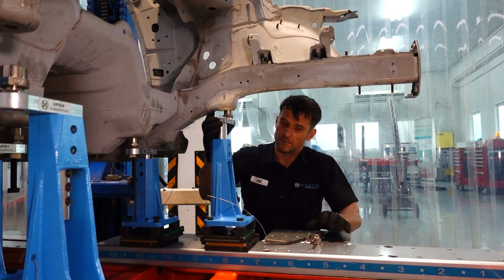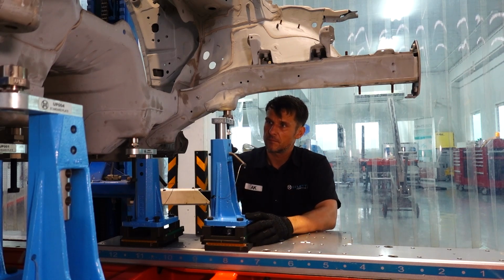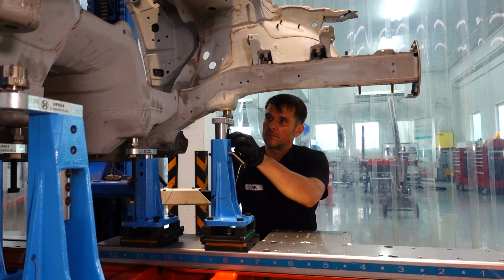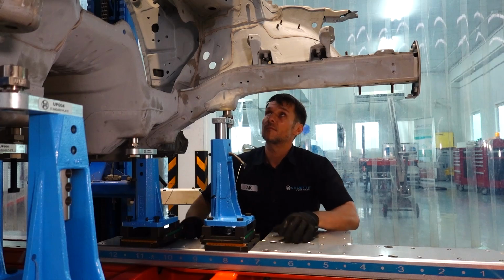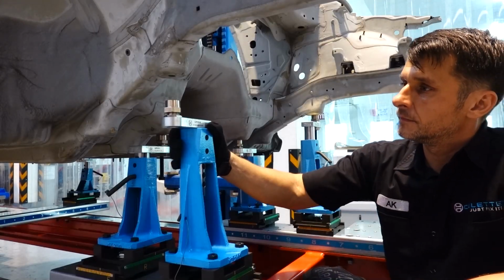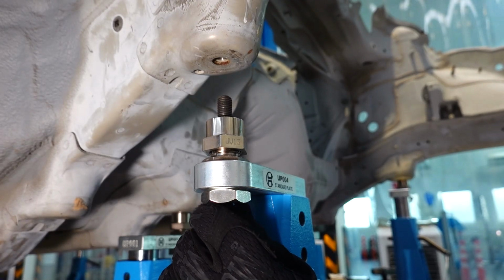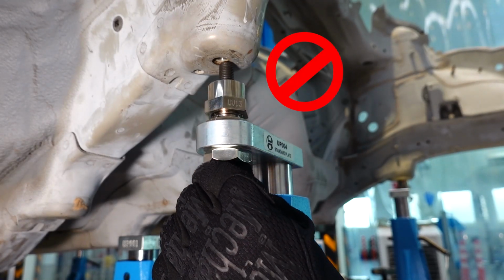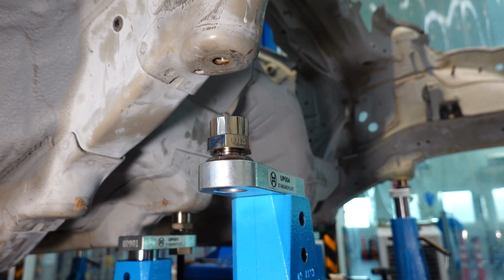Then slide up the pistons of the remaining jigs, fit the socket into the holes, and secure them with the pins. For this jig, we have an example where the screw doesn't fit into the hole because the car has been damaged. In a following video, we'll show you what to do when you encounter this situation and how you can use your Cameleon kit as a measurement system in order to assess the damage.